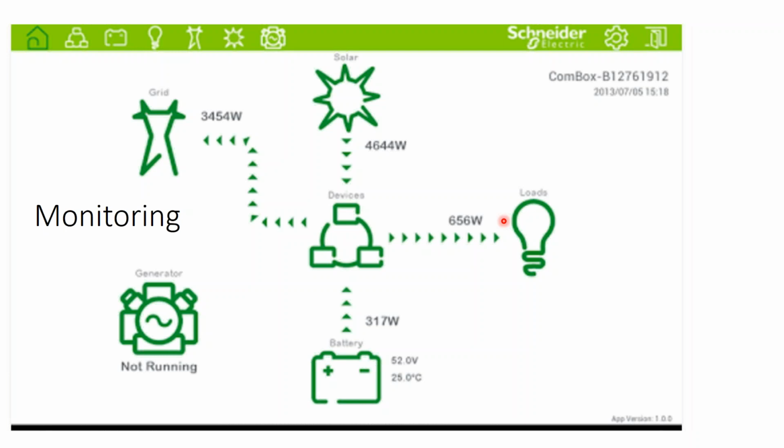And what you want on a battery system is a comprehensive monitoring system so you can easily identify, if you're not getting the power to your battery bank, where's the issue? Is it coming from the solar array itself? Are my loads too big? Or is it an issue within my battery bank itself? It's a lot easier to diagnose that if you're all on the same platform.